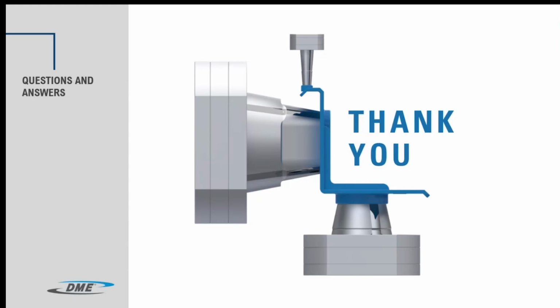Okay. What are the expected service lives of the cores? Generally, depending on the application, there's a lot of influence on how well the mold and the collapsible cores are taken care of. We do expect up to 1 million cycles for each of the S-Core and the DuraCore.